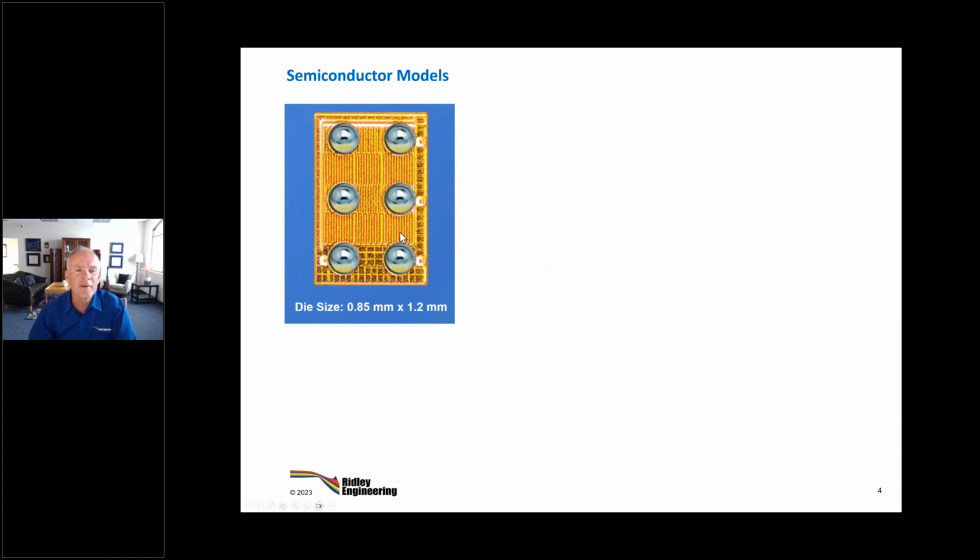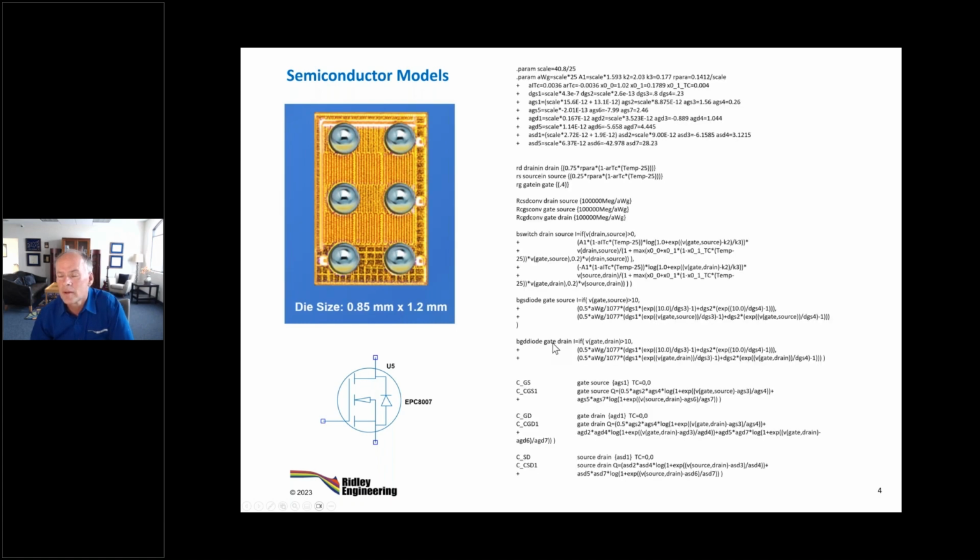Let's just say that if you have a semiconductor part, you want to get into the market and you want to sell to some of the big companies like Apple or Ford or whoever, of course you need a schematic element for it. It's just a regular MOSFET looking here, but this is what shows up in LTspice. And then the first question that the big company is going to ask you is, okay, where's the SPICE model? And even though you've only just finished fabricating your part and making it, you better provide this. Otherwise, nobody is going to try it. They need to put it into the circuit and they need to see what it's doing for them before they get involved in a new technology.